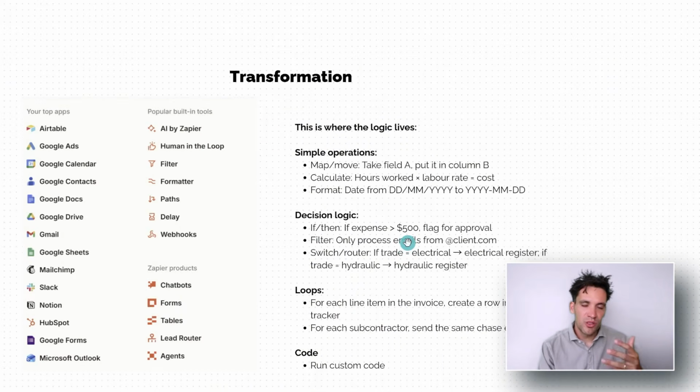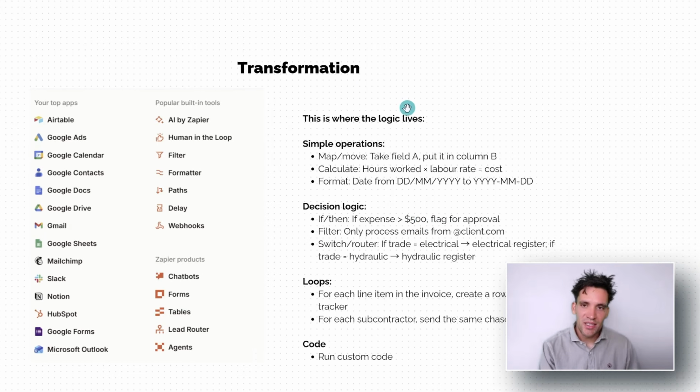The way you should be looking at and thinking about an automation is the transformation of data. As construction people, this probably isn't something we're hyper aware of, but PDFs have different data formats to Airtable records, which have different formats to Procore site diaries. So the key thing we're thinking about with an automation is what is the input data and what is the output data format, and how do we convert between the two?